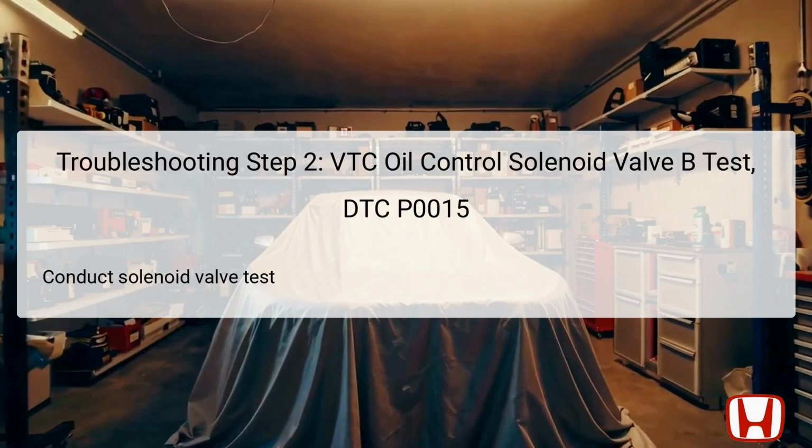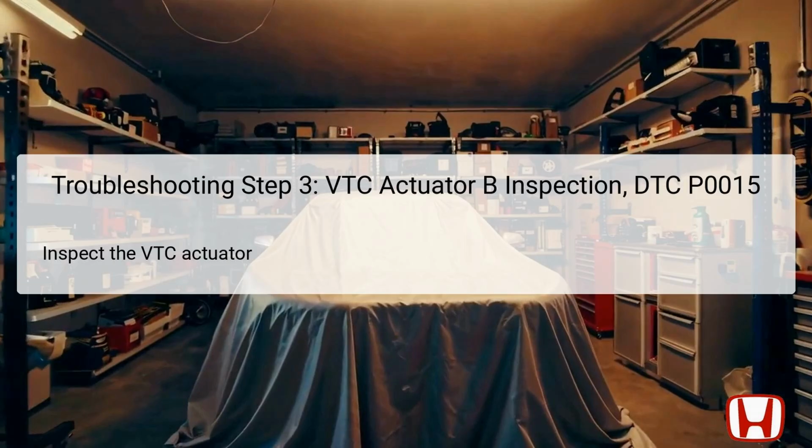the VTC system. Following the solenoid test, the next step is to inspect the VTC Actuator B. The actuator is responsible for adjusting the valve timing based on the oil flow it receives from the solenoid. To carry out this inspection, visually check the actuator for any signs of damage or wear.